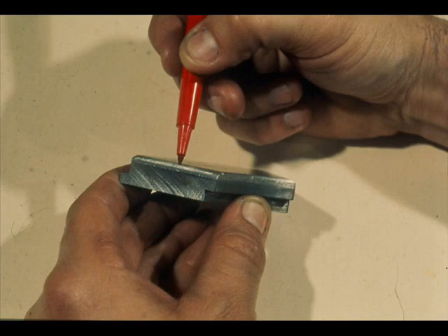The bearing face of the shoes is surfaced with a thin coating of Babbitt as shown here. In new condition, this Babbitt surface is pocked to retain a sufficient amount of lubricant to suffice during startup. The radial edges of the Babbitt surface are beveled or rounded. This beveled edge allows an easy entrance of oil into the area between the shoe and the collar, where a wedge-shaped oil film is formed.